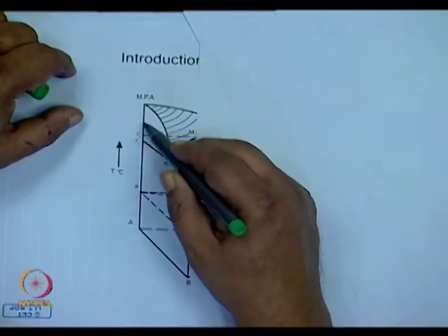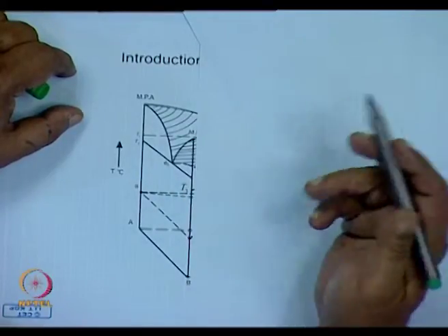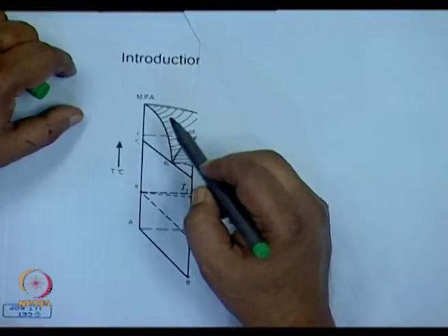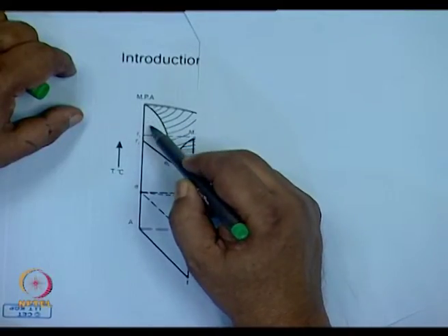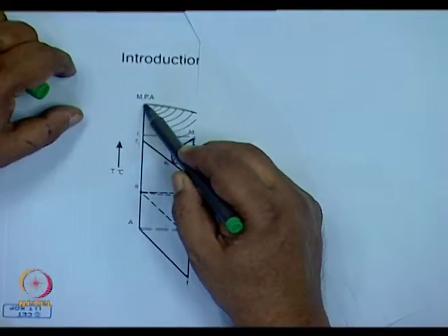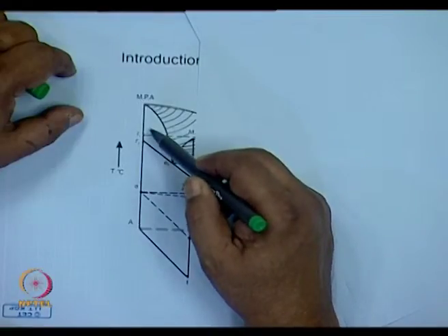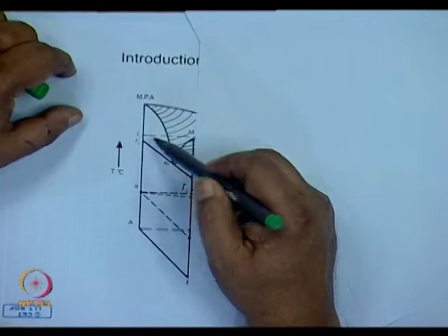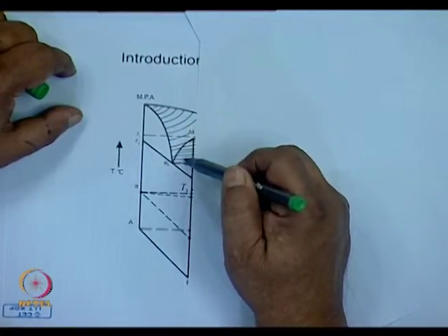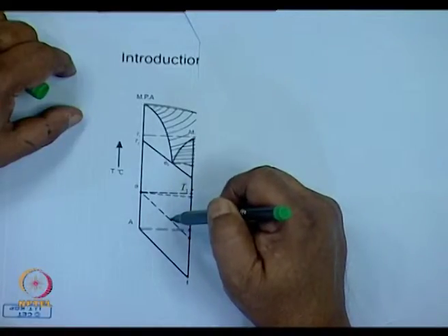So in this two-phase diagram of A and B compounds, which are necessarily oxides, we have this region, this is the eutectic point, this is the melting point of A. So all of this area will be a liquid. This will be liquid plus A. This will be liquid plus B. And then I'll have a mixture of A and B.